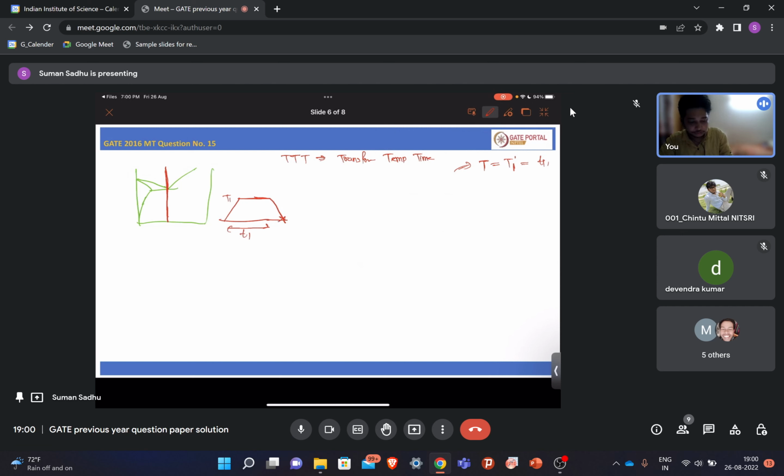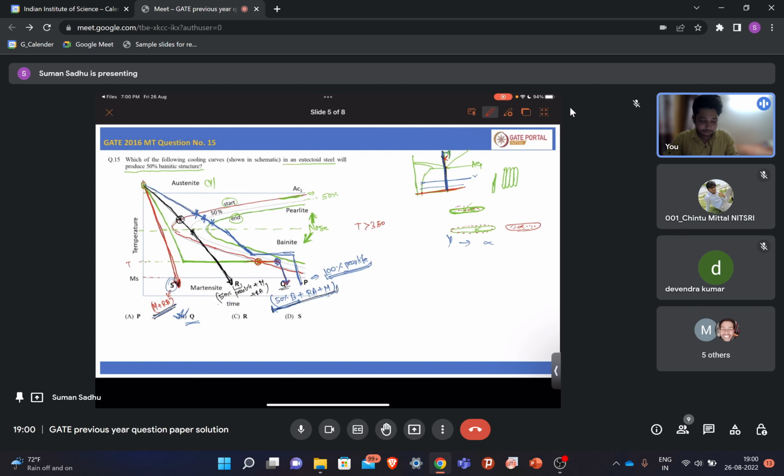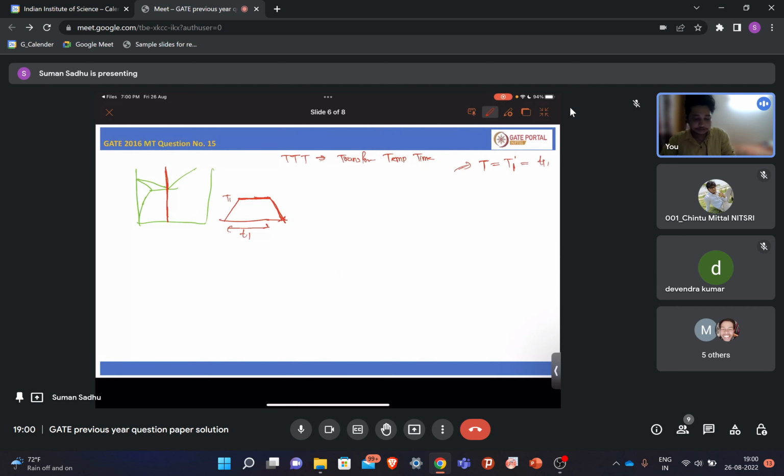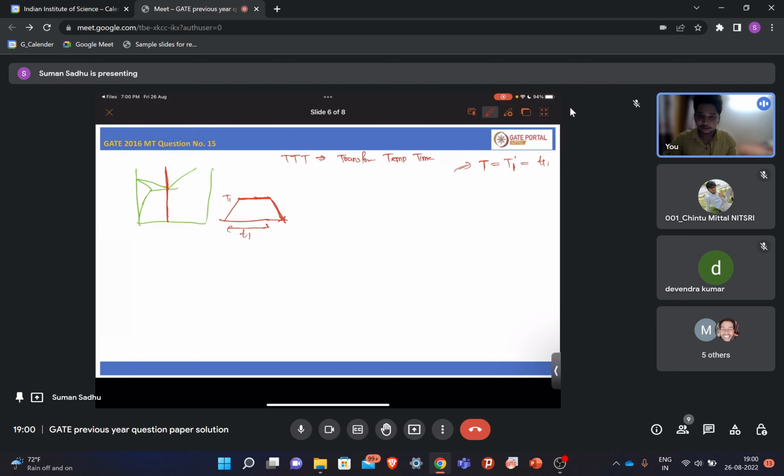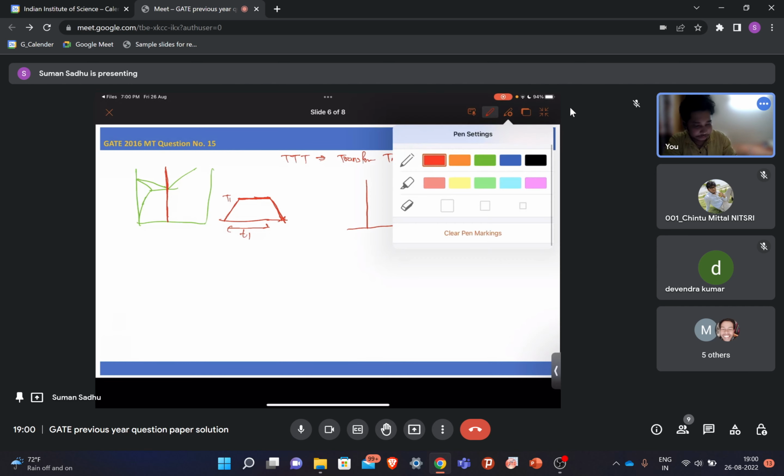So quenching means whatever microstructure is formed at this holding period, that will be retained. It may also transform to martensite, but that pearlitic fraction that is present, as given here in the CCT curve, will not be affected, because upon quenching that pearlite will not change, right? So you will get, now let's say you did this thing for a different set of time.